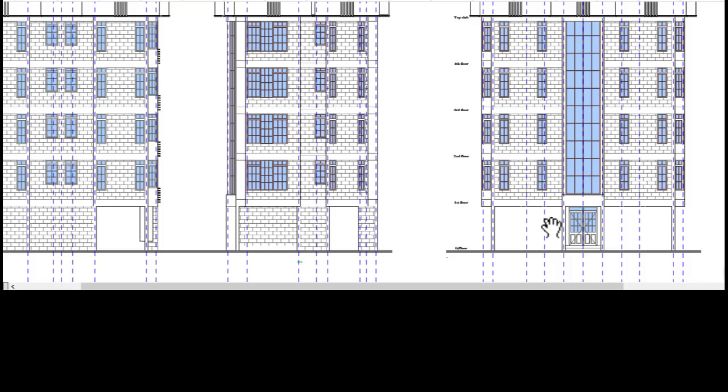So you can always check what is that height from the finished floor up to the beam level, so that you get the overall sizes of the doors. And of course, it's always safer to be on the upper side than on the lower side. So even if the doors will now be shorter than what you have provided as the maximum height from the finished floor level up to the soffit of the beams, then you'll still be safe. So you can always take that full height all the way.